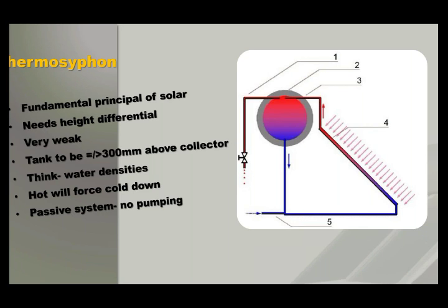And in water densities, we get back to that again, the hotter water gets, the less dense it becomes, and so it floats. Effectively, it floats, because the same amount of water is taking up more space, and if you blow something up, it becomes lighter if it's the same amount of matter inside of it. And that'll always force the cool water back down, and so the cycle continues. So the thermosiphon action is critical in a thermosiphon setup.